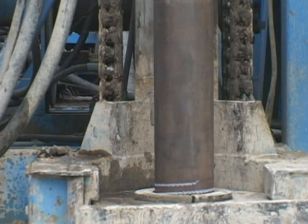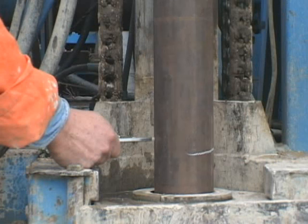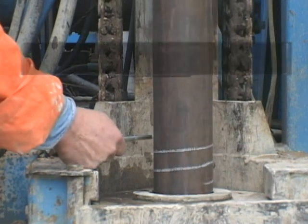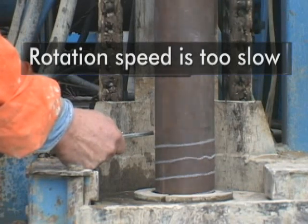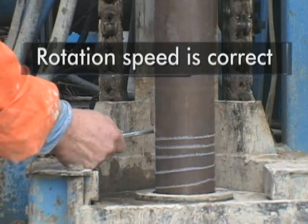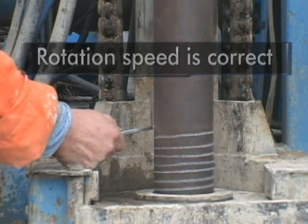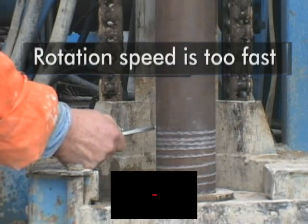The following example utilizes a chalk line to show the correlation between penetration rates and drill string rotation. This example is relevant to a 6-inch hole diameter only. First, too slow rotation for the geology is represented by the wide spacing between chalk lines. Next is correct rotation speed, as shown by approximately 3/8 inch spacing between chalk lines. Finally, excessive rotation speed is shown, as noted by minimal spacing between chalk lines.